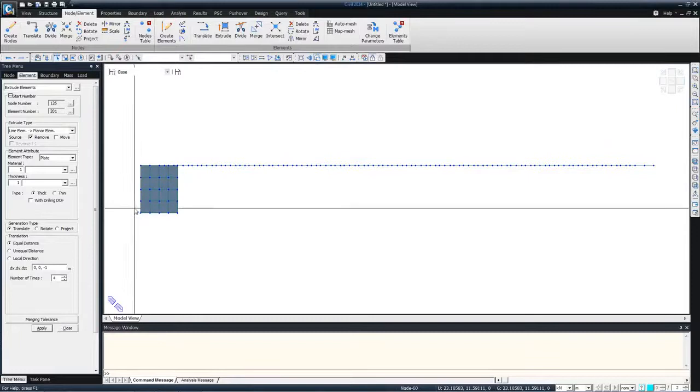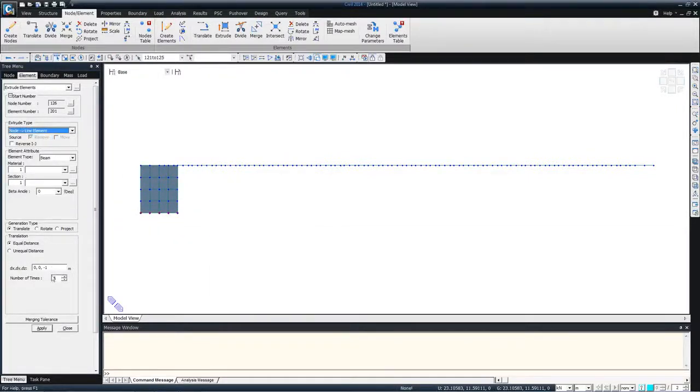So simply copying here and changing this to node to line. Normally we have the soil profile for the pile at every 1 meter interval, so we know how the subgrade reaction changes at 1 meter intervals from the soil data. Because soil structure interaction is very important for integral bridges, we have to consider a good amount of accuracy when assigning the soil springs.